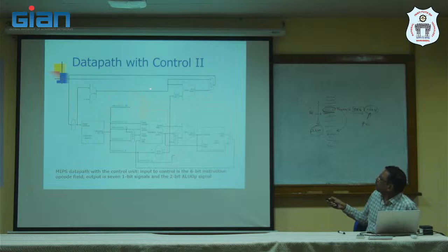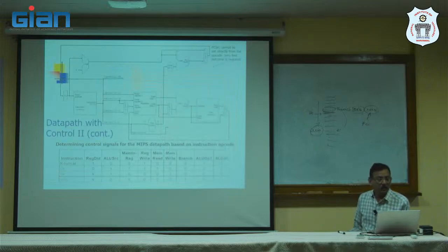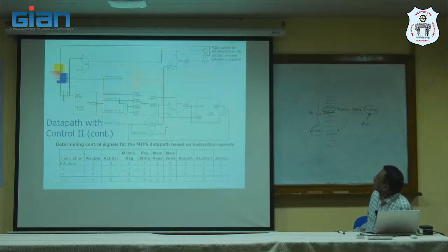Okay. So from this it is generating ALU OP, 2 bits. Then the 6 bits of the instruction field and ALU OP go to another controller, the ALU controller. This will generate 3 bits of ALU control. This is the main controller and sub controller, the 2-level controlling. So then you can write all the bits, and also you can develop simple combination logic.